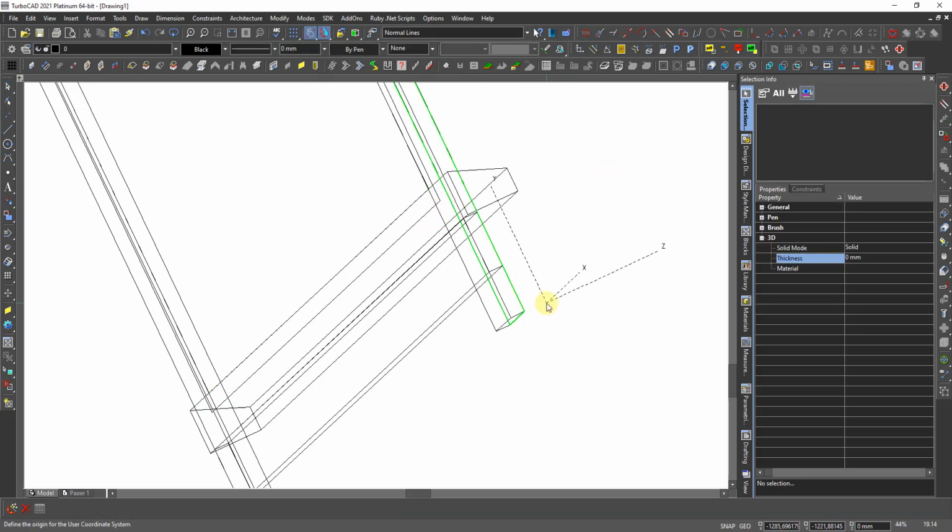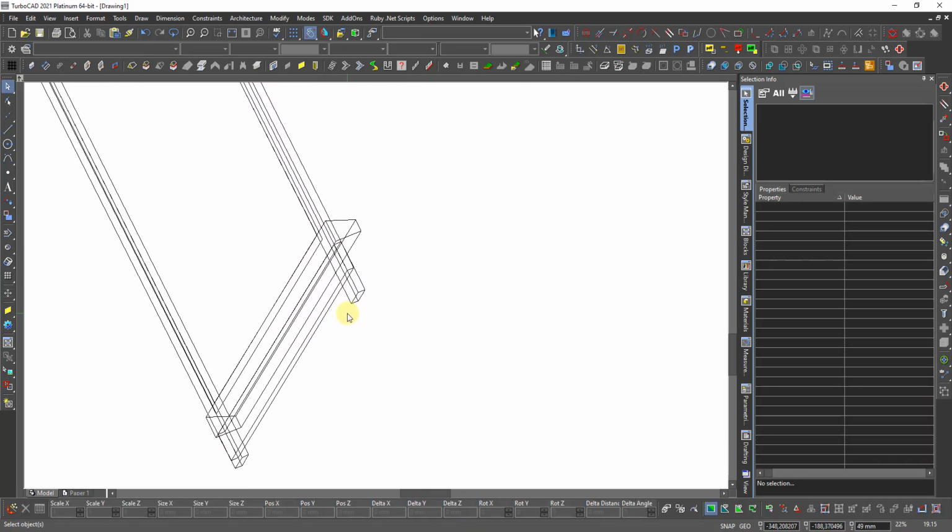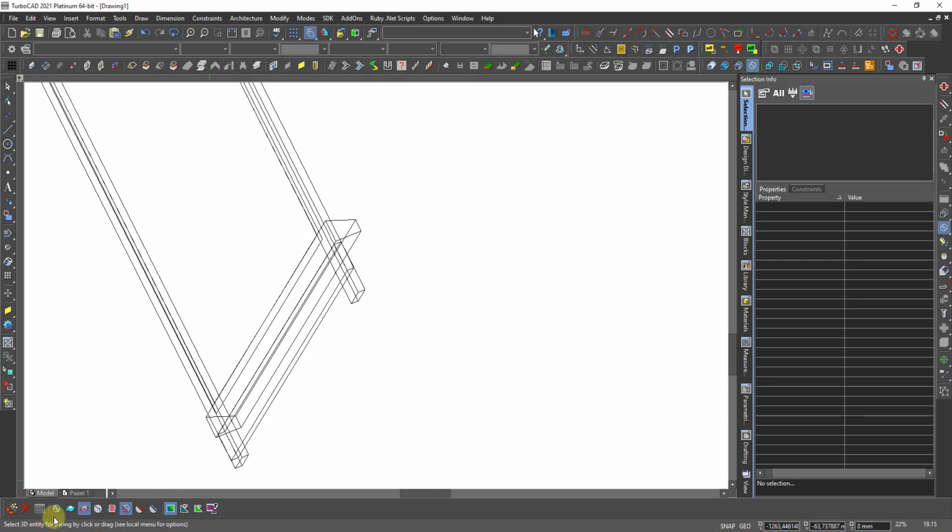Now I get confused by the view. It is there. Because I slice, this will automatically be an ACIS solid. But just to be sure, so we don't forget anyone, because if they are not correct, then they will not work. Simple as that. So then I say slice, and normally it comes with slice by 2 point, but I set it to slice by work plane, and also say delete sliced part.